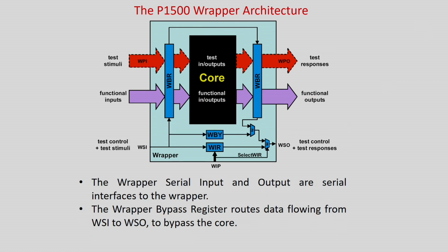Okay, and then one more important thing I should say is how to give the instructions. They are actually in a serial mode, because it is already told that at least the serial mode of access to all the chip cores through the wrapper must be available. Parallel is optional, but sequential is a must. So therefore all the instructions are given in a serial mode.